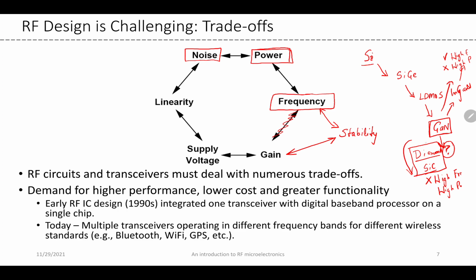For example, you'll see power devices which don't require high frequency applications. So power applications are increasingly being researched using diamond or SiC, or there are other devices like gallium oxide. So we are trying to make new devices using these materials. And then towards the high frequency side, we're looking at InGaN or similar materials, and we're trying to improve their power performance. And that's again a field of research that's going on.